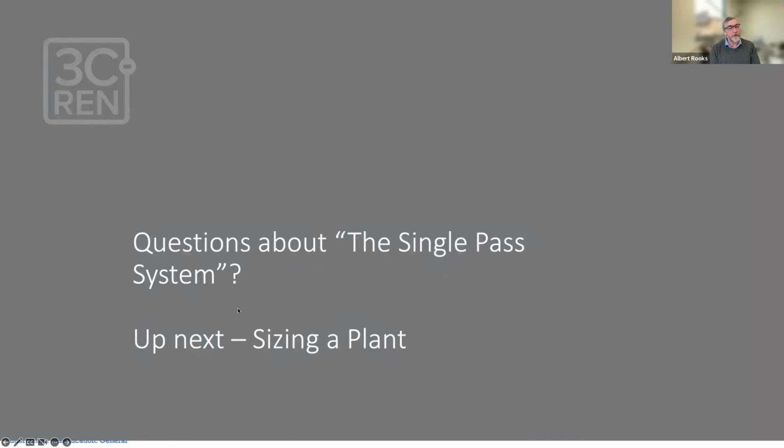So Zach's asking, does this system have CTA 2045 for demand response? It's being built in right now. Everything will have CTA 2045 for demand response. We've got a project in the shop right now that we're building these package plants for. It'll probably be the first in California that has CTA 2045 and load shaping. And fortunately, the plants were oversized, so we got extra primary storage, so we can actually use the CTA 2045 to shape the utility load.